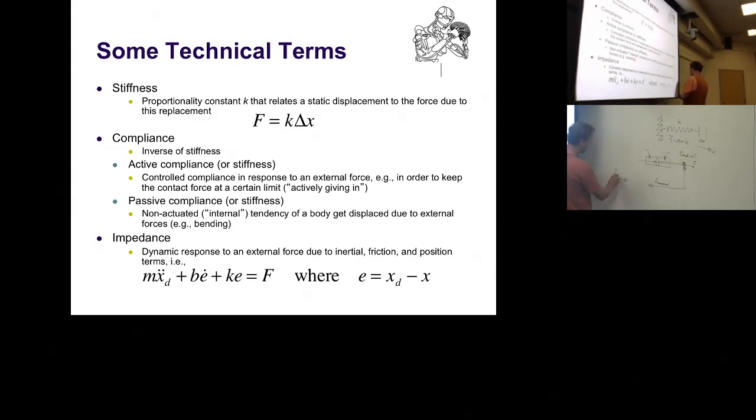And here's something like F desired. You compare: this is plus, this is minus, and then you correct with your motor control input to the system. And that becomes an active regulation. It's also done in robots which have gearboxes. We have a bunch of hydraulic robots where this is done. You will hear that gearboxes may actually actuate as stiff as hydraulics.